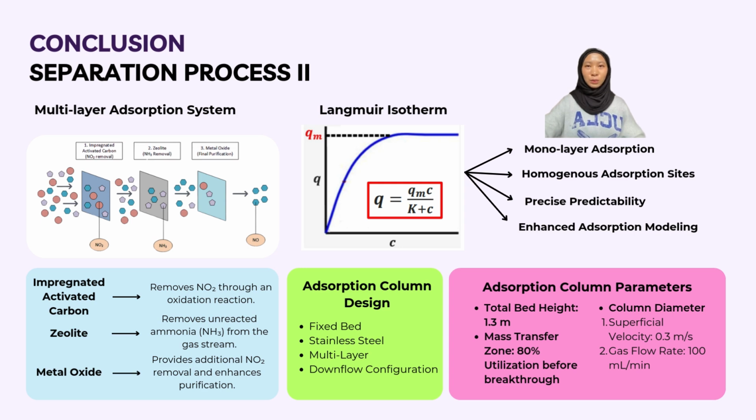The reason we chose the Langmuir isotherm for this project is that although our system involves multiple adsorbent layers such as zeolite, metal oxides, and activated carbon, each layer functions independently as a monolayer. This aligns well with the assumptions of the Langmuir model.